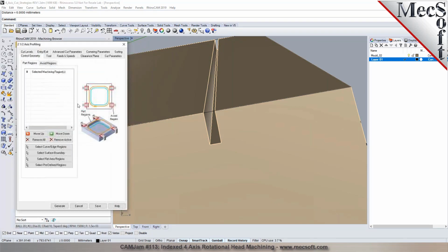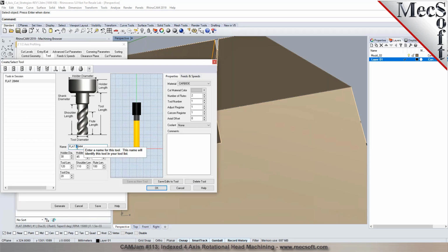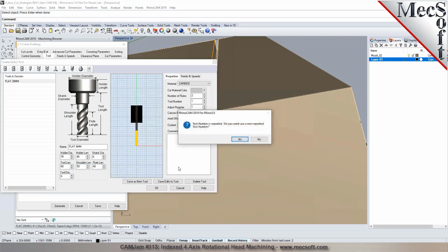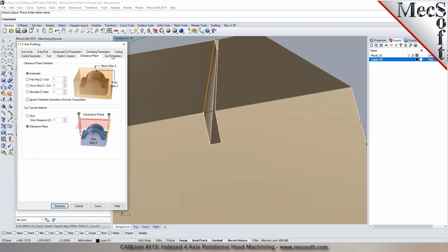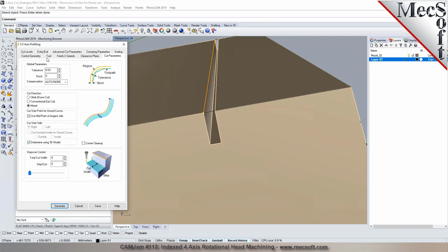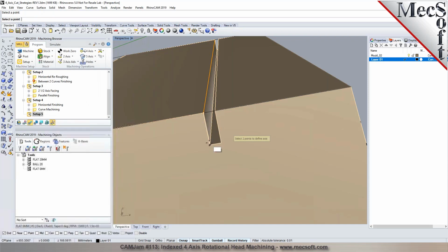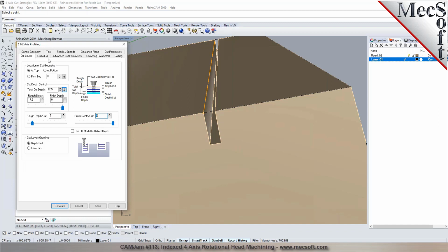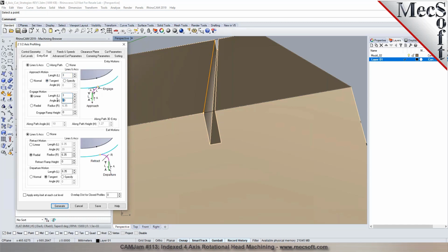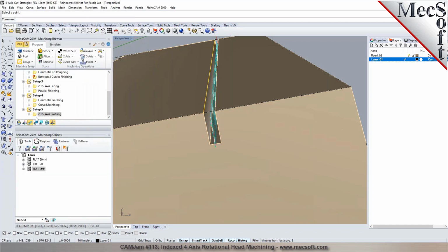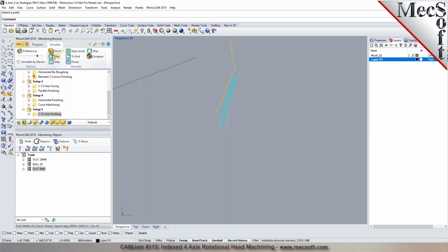Yes. And we can program a profile cut to cut it in one pass in multiple steps. So I can just pick that edge, create a tool, a 6 mil flat tool. And this doesn't have to be that long, so I can say just 60 millimeters. We'll save this up. That's a new tool. And then everything else would be very similar. And you can choose the cut levels in here. So when you measure the depth, it's going to be along the tilted plane. Okay. And you can say you want to go in multiple steps of 3 millimeters each. You can control your entry and exit however you want it to. Lead in, lead out, so we can have a slight retract outside, so it gives you a nice clean edge, and then generate it. So that'll give you a profile cut at that angle. Yep, perfect.